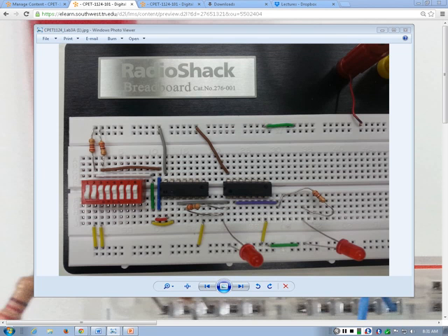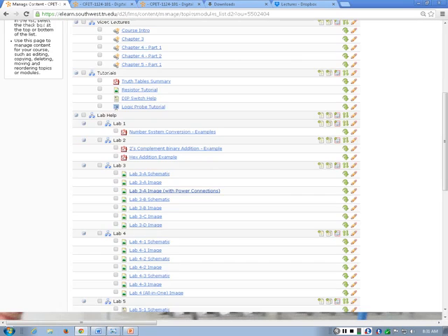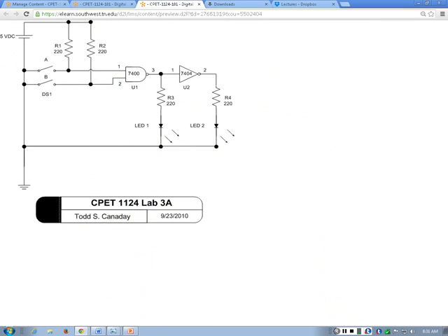Okay? So similarly, if you go to the schematic, you will see exactly the same thing in the schematic as well. Look at this. You might be wondering how the LED comes into the picture. With this point between pin 3 and pin 1, we basically ran another wire through the resistor to the LED. Do you see that? To the ground. Because we basically want to check this point.